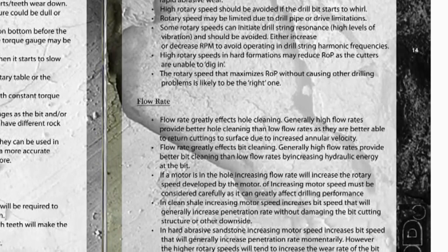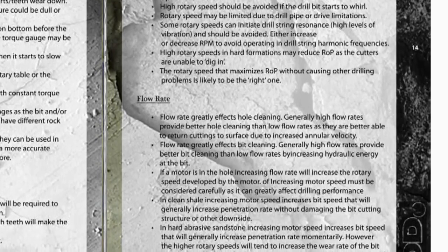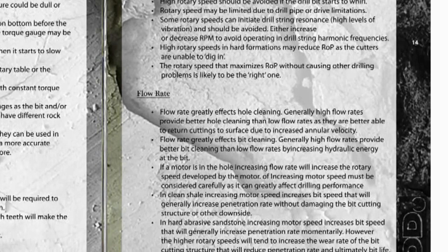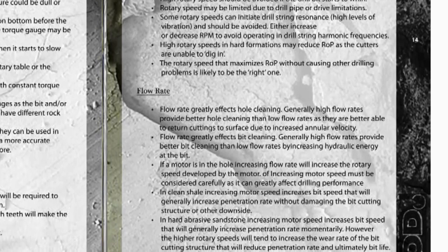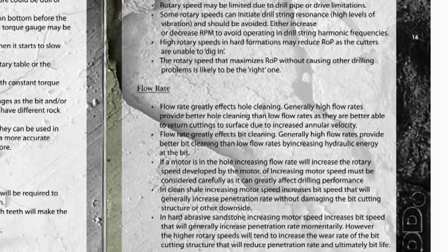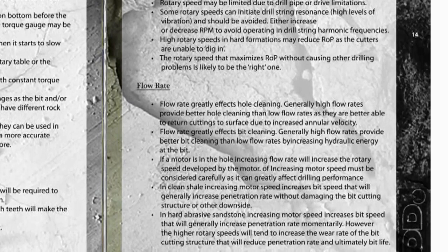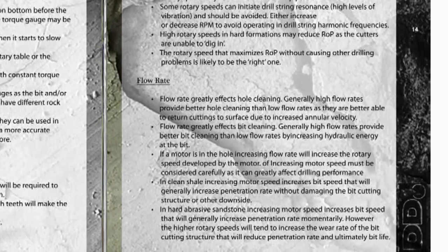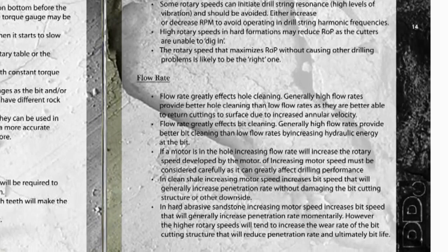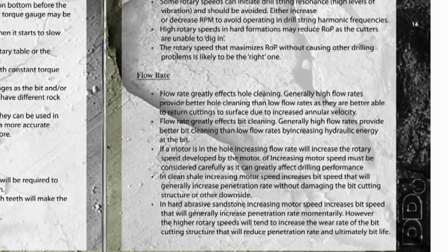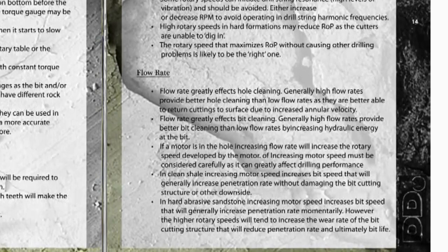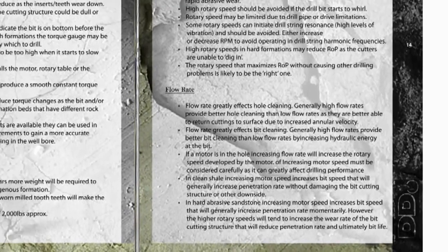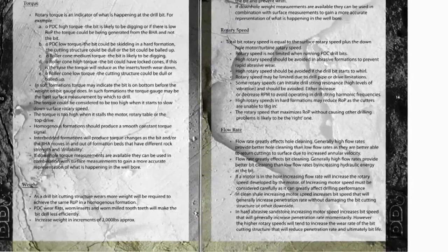In clean shale, increasing motor speed increases bit speed. That will generally increase penetration rate without damaging the bit cutting structure or other downside. In hard abrasive sandstone, increasing motor speed increases bit speed. That will generally increase penetration rate momentarily. However, the higher rotary speeds will tend to increase the wear rate of the bit cutting structure. That will reduce penetration rate and ultimately bit life.